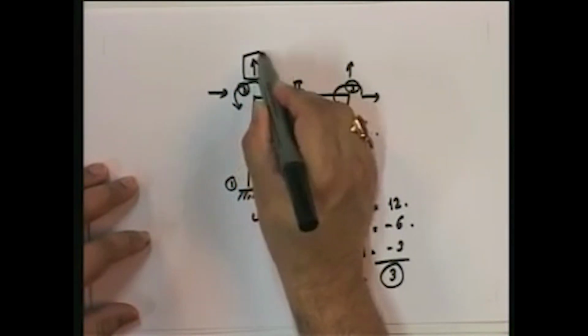How do I make them disappear? Remember, it's not 3 displacements that I'm making equal to 0. It may so happen that 2 displacements are equal to each other, in which case it is only 1 degree of freedom. Because remember, the kinematic indeterminacy is the minimum number of independent displacement quantities that I need to define to be able to give the displaced geometry. Now if 1 degree of freedom is equal to another degree of freedom, then what happens? I need only one of them, right? Okay, so therefore let's look at this. Now let's look at this degree of freedom. What does this entail?